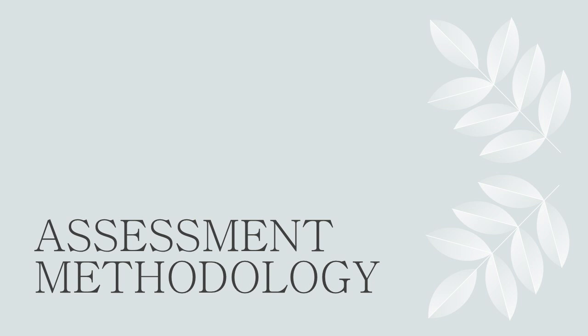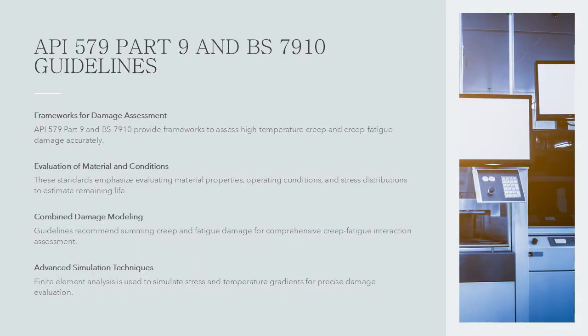Assessment methodology, API 579 Part 9 and BS 7910 guidelines. API 579 Part 9 and BS 7910 provide comprehensive frameworks for assessing high-temperature creep and creep fatigue damage. These standards recommend evaluating material properties, operating conditions, and stress distributions to estimate remaining life. Key steps include determining creep rupture data, calculating stress intensity factors under creep conditions, and applying damage accumulation models.